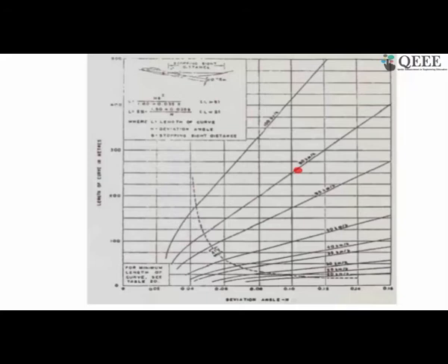Now a few other questions which I got. One is, from the safety point of view, which curve is more feasible, valley or summit curve? From the comfort point of view, as I told you, the summit curve is better. From the safety point of view, it all depends on the speed. If you are at a higher speed than the speed the curve is designed for, on a summit curve your vehicle can be thrown off the road.